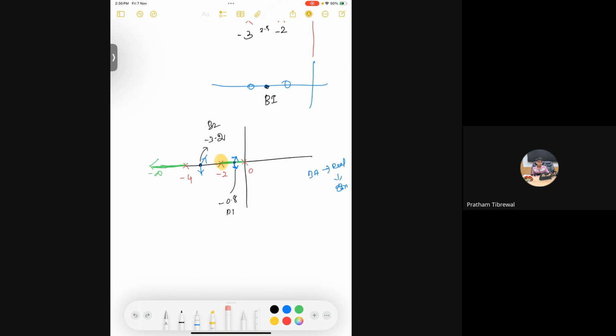Right. So here two breaking points will come now. We have this here and it is going to break like this. But the minus 3.2 is not valid. Why is it not valid? Oh, it's not in the root locus. Yeah, I missed that perspective. Right, you're right. So we are just leaving it. If it is not inside the root locus, we won't consider that. If it is here, then it will be another breakaway point. Okay, thanks for pointing it out. Good.